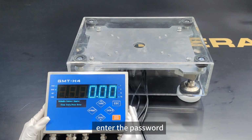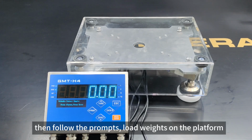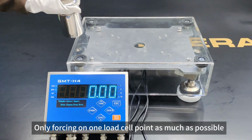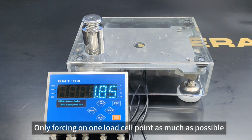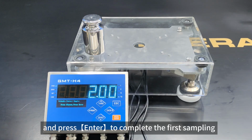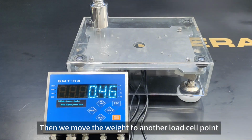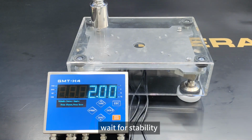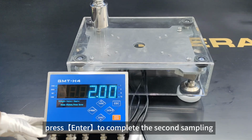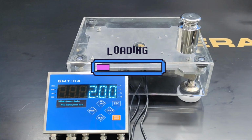Enter the password. Keep the scale empty. Press Enter to confirm. Then follow the prompts. Load weights on the platform, forcing on only one load cell point as much as possible. Wait for stability and press Enter to complete the first sampling. Then we move the weight to another load cell point. Wait for stability. Press Enter to complete the second sampling. Repeat the above operation.